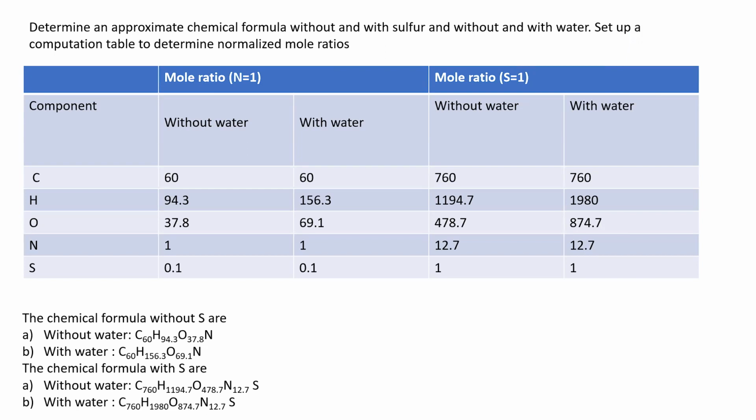Fine, ma'am. And the syngas production is exothermic, right, madam? Combustion, if you are converting CO to CO2, is exothermic. Syngas production, we are providing heat and we are getting the syngas at a temperature of around 200 to 350. Yes, the syngas outlet from the reactor can also be used for preheating the feed.